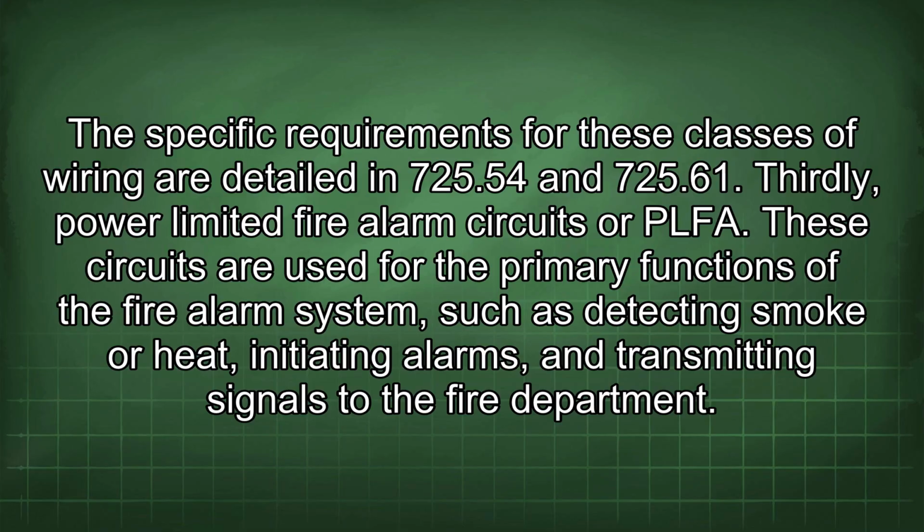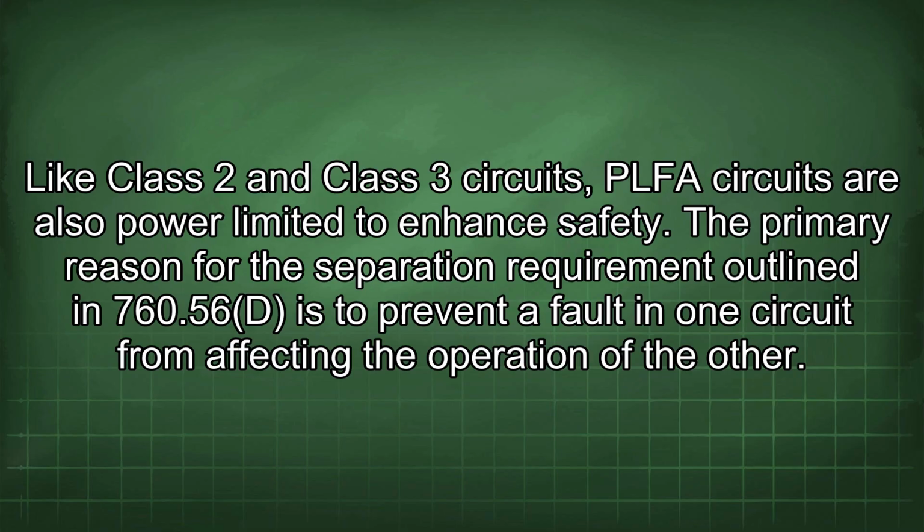Thirdly, power-limited fire alarm circuits, or PLFA. These circuits are used for the primary functions of the fire alarm system, such as detecting smoke or heat, initiating alarms, and transmitting signals to the fire department. Like Class 2 and Class 3 circuits, PLFA circuits are also power limited to enhance safety.